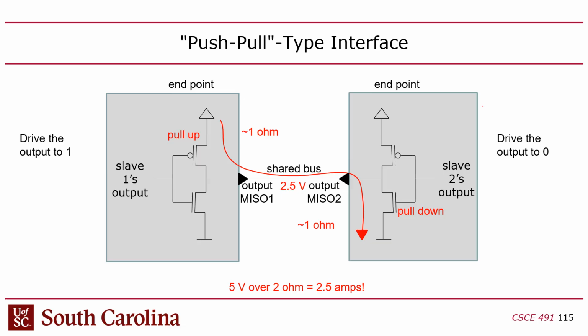This is the part that I think is kind of confusing: essentially you've created a short circuit here, but the short circuit is not inside of one chip. The short circuit is created from the participation of two separate chips. And so current will start roaring out of this first chip that's trying to pull up, and it'll start sinking down into the chip that's trying to pull down, right?